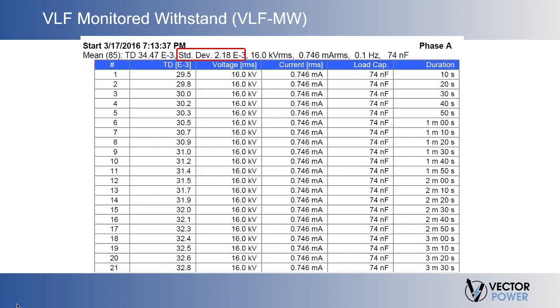So the cable is actually getting weaker as we've been raising the voltage, and particularly here over the course of time, we are seeing another effect taking place. Notice the voltage is not changing, but the tan delta reading is slowly beginning to increase, indicating weaker dielectric strength, higher losses or higher resistive currents flowing.